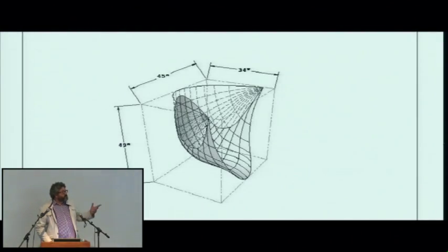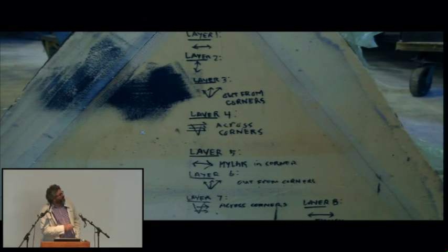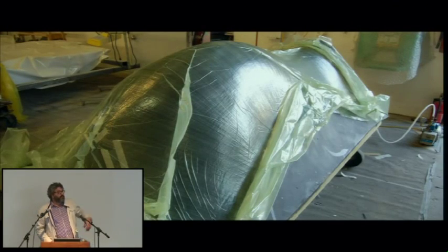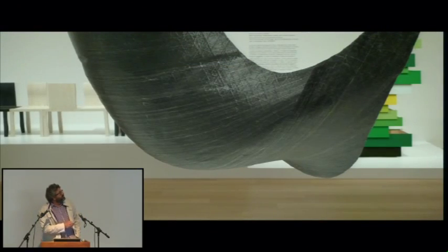The other are these chairs that we're doing using a tape technology of carbon, where we take very thin, fragile, pre-impregnated carbon tapes and lay them up in a schedule of orientations based on their load and put them on a rigid tool. It's just a foam tool that we cut in my office. Then you put it in a bag and cook it at a couple hundred degrees, and it consolidates all these fibers. And you end up getting these hanging chairs, which, unlike a piece of fabric, work as a compression shell under their own load.